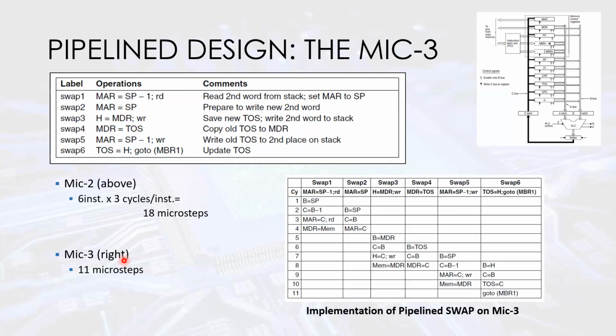For swap 1, did we want to write MDR equals MAP because of the read on the line above it? Yeah, so it's just implicit when you do a read command in this microarchitecture. What that means is, hey, you're going to read, and eventually that result is going to come back and you're going to find it in the MDR at the end of the next stage. And likewise for a write, whatever's in the MDR, I'm writing that out to memory. So that's why we have that syntax. Okay, any other questions on this notation?